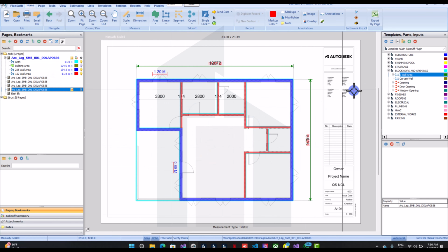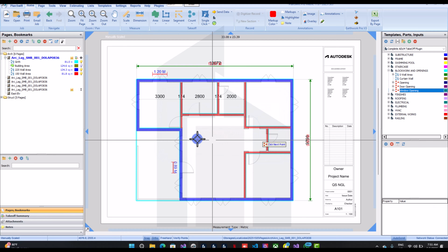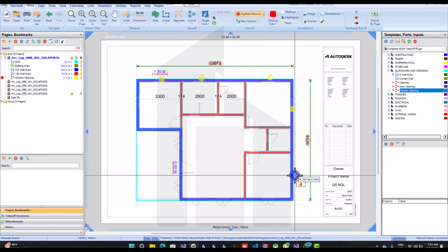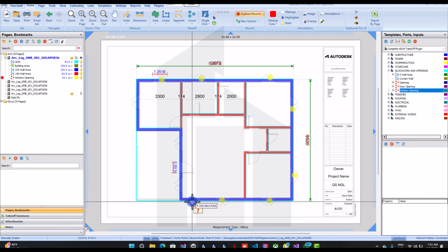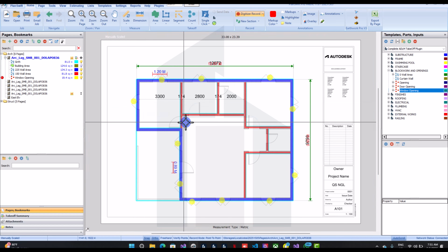So basically with that, just come down to windows for window opening. Window width is 1.2. The height is 1.47. Number of floors is 1. So the wall changes to opening. Okay, good. This, just count this like this. All the windows are the same size. Okay, good.